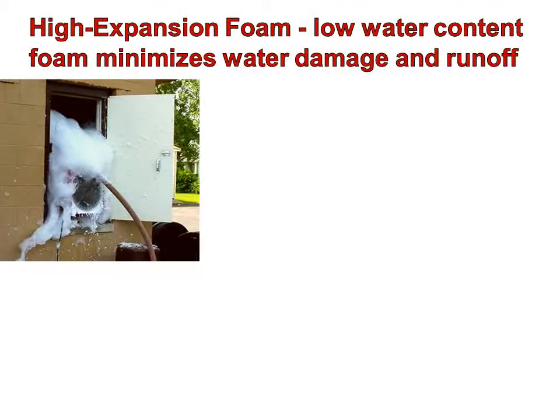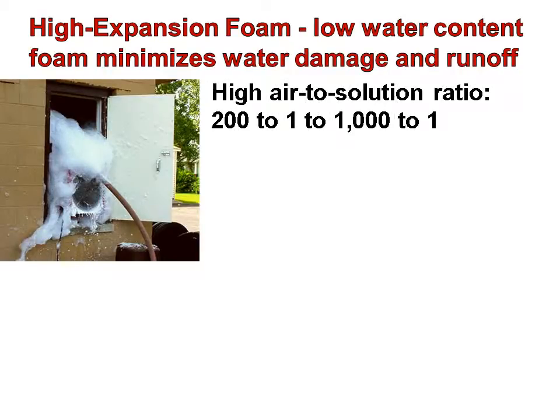High expansion foam, lower water content foam, minimizes water damage and runoff. High air to solution ratio, 200 to 1 to 1000 to 1. It's got a poor heat resistance. Will attack the surface of galvanized steel and raw steel with prolonged exposure.